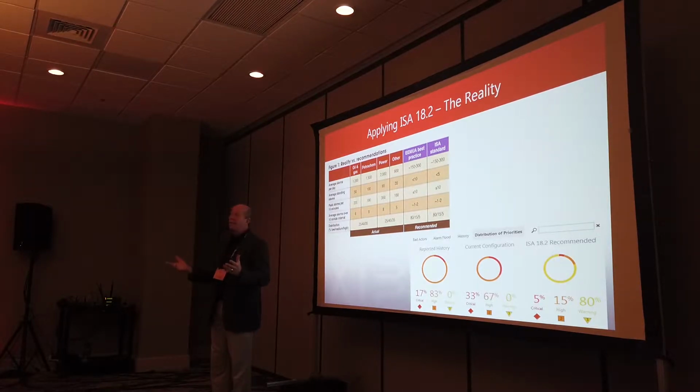So you could actually take that now and say, wow, if the system that I'm either working at or interfacing to is having more than 1 alarm every 2 minutes, I might want to take a look at how that's designed. And can my operators really keep up with that? They would call that operator fatigue, by the way, operator fatigue.